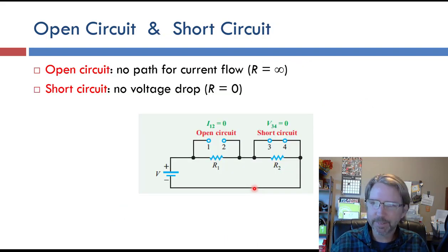Since we're talking about resistance again, I think we saw this in a previous lecture, but remember, an open circuit or cut wires can be modeled as an infinite resistance. So we can talk about this resistor being in parallel with this resistor that's infinity, and we can apply the equivalent resistance formulas that we'll see soon. And same thing with a short circuit. You could think of that as a resistor with a value of 0, and then you can do all of your analysis using 0 in there and see how the circuit turns out.